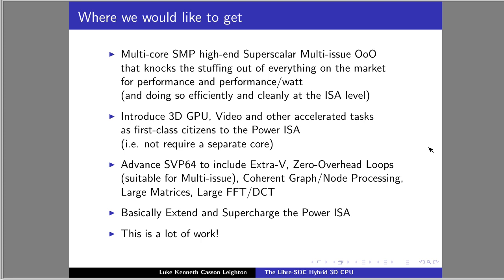So you want your 3D instruction, right? Call it now, there and there. It's done. No context switching, nothing. So this basically will be adding floating point cosine to the Power ISA. We will be adding floating point ATAN2 to the Power ISA, not make it call and have to get the answer back several microseconds later, once it's come out of a queue along with 10,000 other tasks. Yeah, much cleaner design.